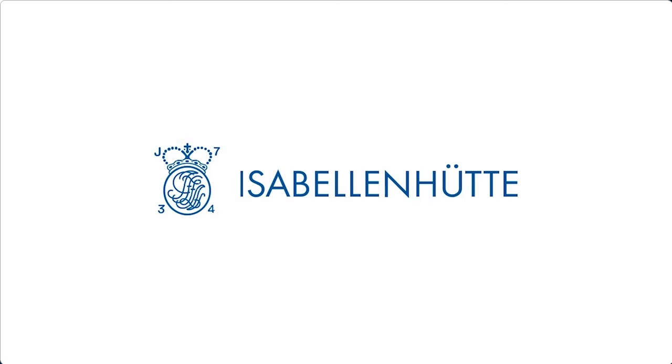Thanks, Matt. That's a great question. So yeah, there's definitely a couple of advantages if you use a smart sensor over an analog sensor in a BDU. For one, the AD conversion is done right in the module. So that means you're definitely less prone to have any magnetic interference in the signal. And also you get a high accuracy output as the calibration is done right in the module. So you don't need to worry about any calibration in your microprocessor.